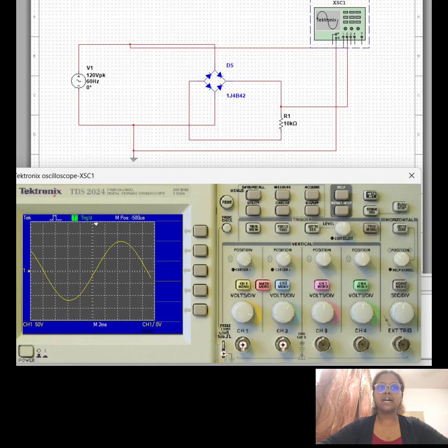As I explained before, there are 2 types of rectifiers, which are half-wave rectifier and full-wave rectifier. Full-wave rectifiers require numerous diodes, while half-wave rectifier just needs one. In contrast to full-wave rectifier, which rectifies both positive and negative cycles of AC, half-wave rectifier only rectifies one cycle of AC. In a half-wave rectifier, the current through the load is not continuous, but in a full-wave rectifier, the current through the load is continuously flowing, opposite to the half-wave rectifier.